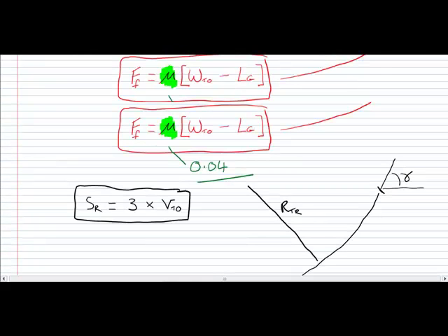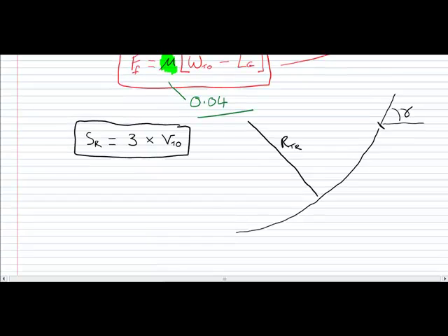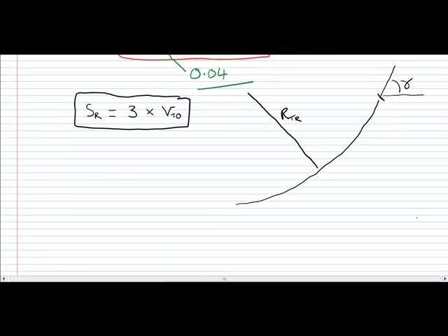Now the first thing that we can think about, if I can get that back, is what kind of, well, let's draw the aircraft in. So our aircraft has its thrust vector angled in this direction, its drag vector acting in that direction, its lift vector acting perpendicularly to the flight path direction. Oops, sorry, this should have been drag, and weight acting vertically down.